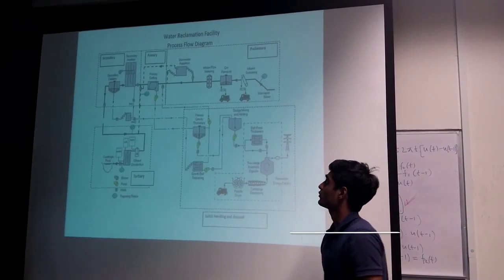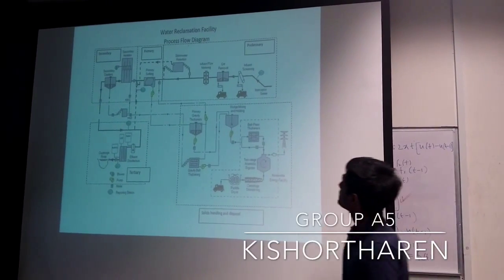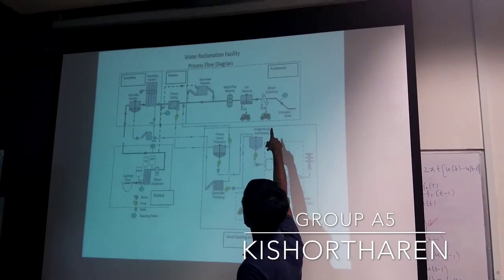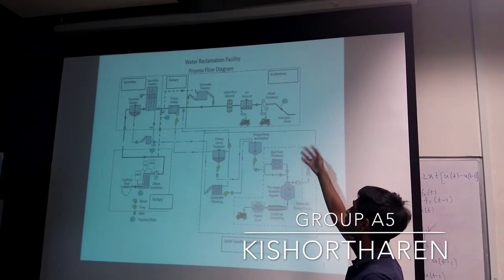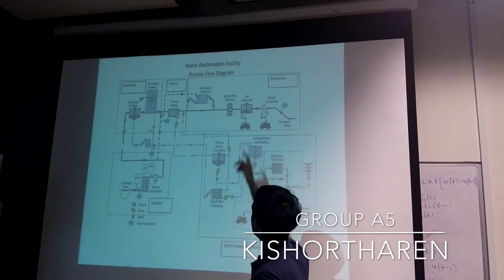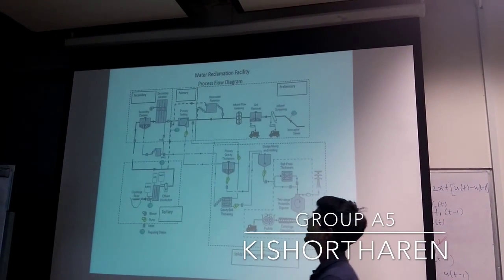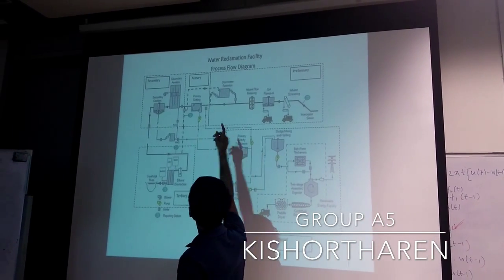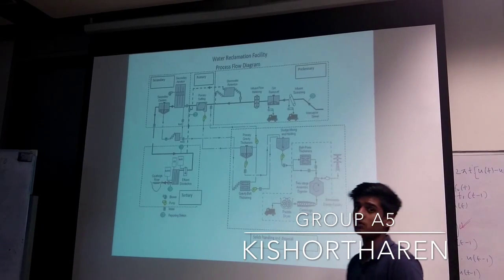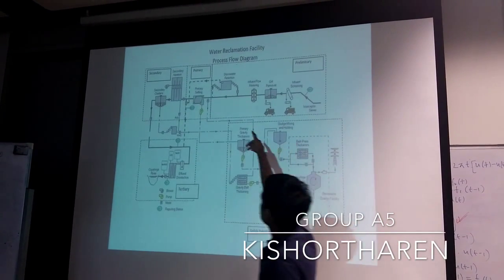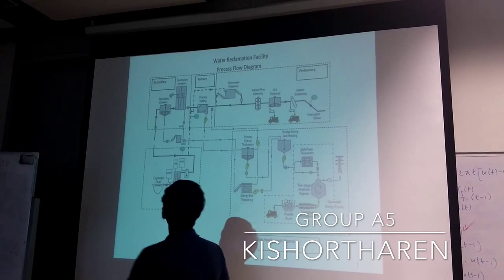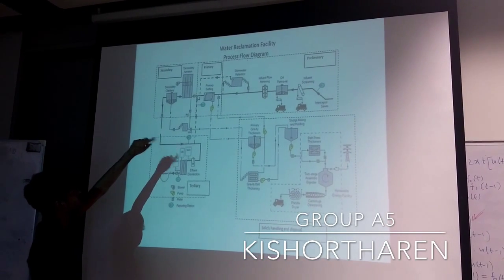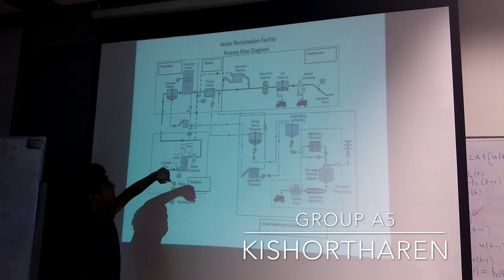Of the wastewater treatment plant. First, the water enters the preliminary stages. As you can see, the water enters the screening process where rocks or any other unwanted items are removed, and then goes to the grit removal tank where sands and rocks also are removed to prevent clogging, and then it moves on to the storm retention tank where the flow is equalized. After that, it enters the primary stage where, as you can see, sedimentation occurs with the help of gravity.